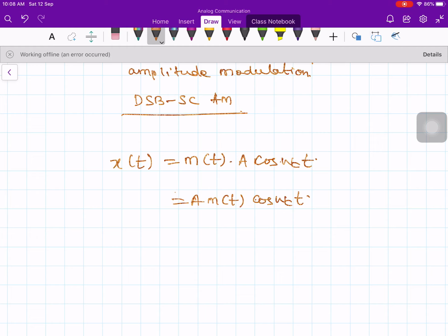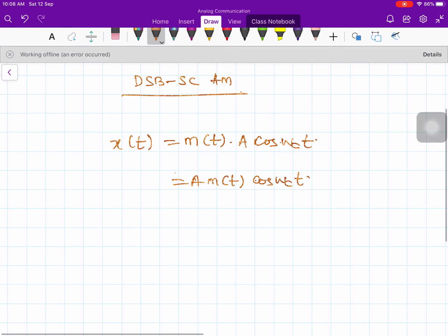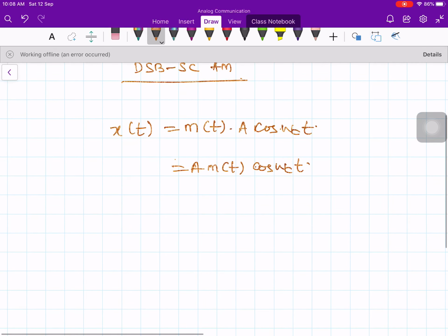In the modulation we have done the frequency translation. The same kind of opposite frequency translation process we need to do here, so that we get the component around 0 Hz frequency. That is the baseband component. Of course, in the process we will get a component around 2 fc as well. Therefore, the demodulator will have the same multiplier that we have at the transmitter.